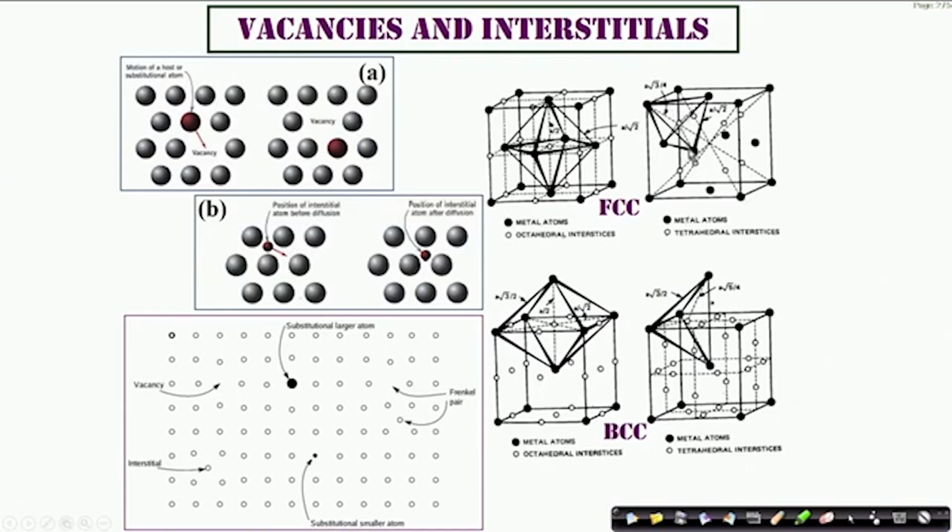And since this is geometric, where we can actually calculate exactly the length of these arms, we also should be able to calculate exactly what's the diameter of these vacant sites. So this kind of interstitial position, their size, their location can be geometrically determined using such considerations both for FCC, BCC and for that matter any other kind of Bravais lattices.